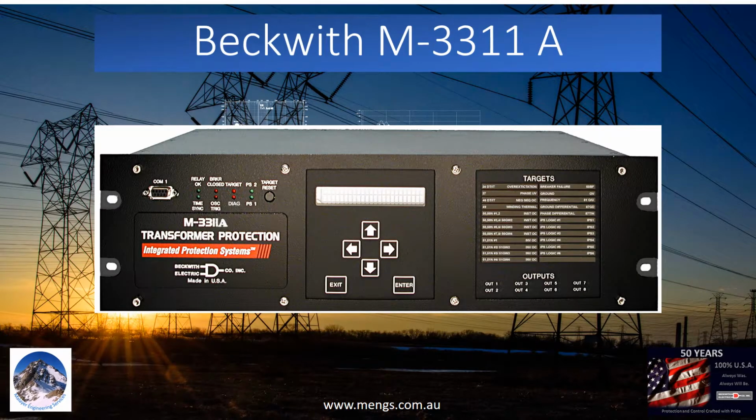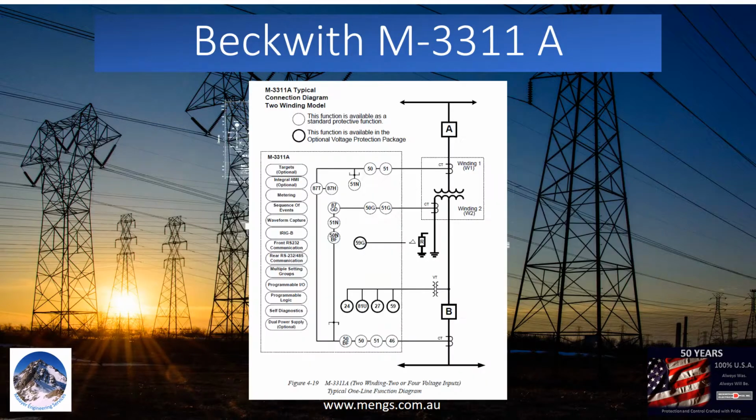Beckwith M3311A is an advanced transformer protection relay. It can protect transformers with 2, 3, or 4 windings. Beckwith M3311A provides dual slope restrained differential, high set unrestrained differential and restricted earth fault differential elements, which provide excellent unit protection.